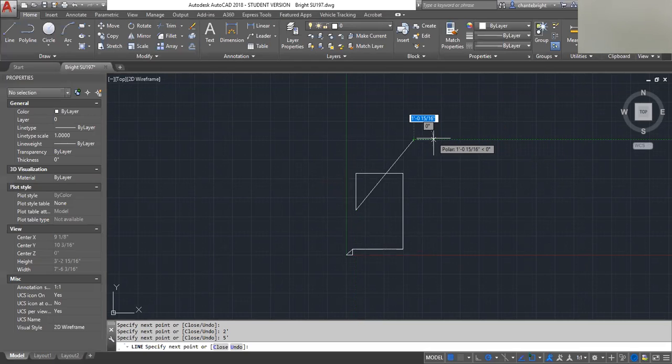If you want to get specific when it comes to the angles, where someone tells you it's about 7 feet in a 35-degree angle, what you want to do in this particular case, and these are called the dynamic input blocks, is hit the tab key. When you hit the tab key, it's going to take you to the next dynamic input, which in this particular case are degrees. And remember I said, well, it's going in a 35-degree angle, right? So I'm going to type in 35 degrees. And then I'm going to hit tab again.